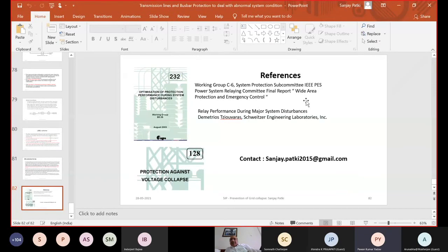So is the secondary transformer star connected or delta star? Sir, the secondary transformers are delta star connected, but actually, sir, in the 33 kV transmission line, we have implemented an open conductor scheme in which, along with negative sequence, we have taken undercurrent also. While charging the 6.6 kV to 415 volt transformer or the step-down distribution transformers, our line always trips on open conductor fault.